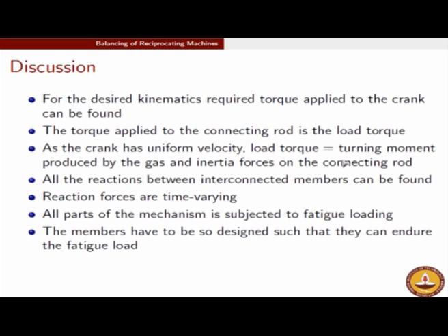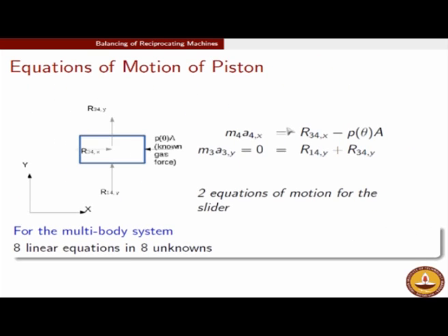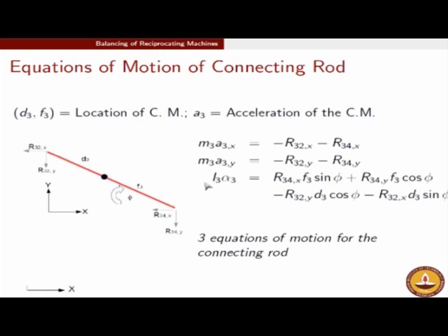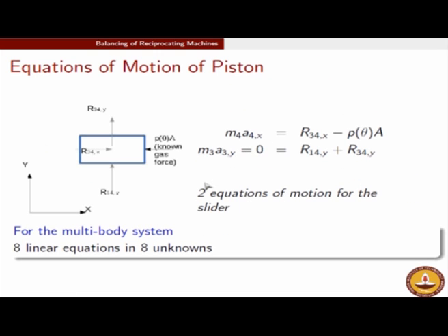So if I look at the free body diagram of the crank, which I will bring up again in a moment. So this is the free body diagram of the crank. This blue arrow is the load torque m, which we have found. All these forces taken together, rather these two forces taken together, will form a turning moment, right? And this turning moment and this moment have to balance such that the crank is rotating at a constant angular speed about this point, and this is what we will try and achieve through our flywheel.